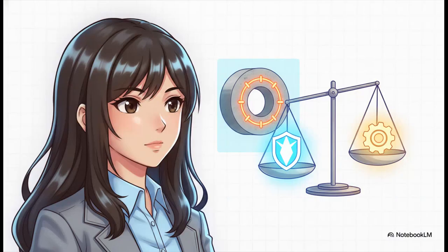Okay, so the ultimate check guarantees it won't collapse, but it's up to you to test the limits. Because our resistance was so much higher than our required moment, we definitely have some room for economy here. So here's a homework challenge for you. Try running the numbers again, but with just 8 strands instead of 10. Does it still satisfy the ultimate condition? See if you can hit that sweet spot balancing flawless safety with economic efficiency. That's what true engineering is all about, right?